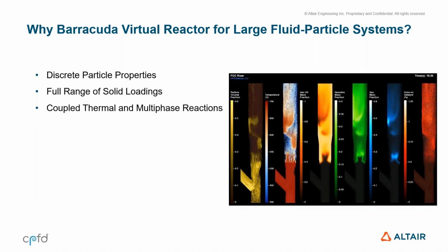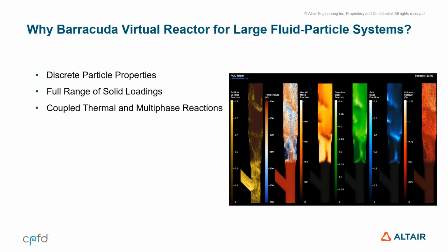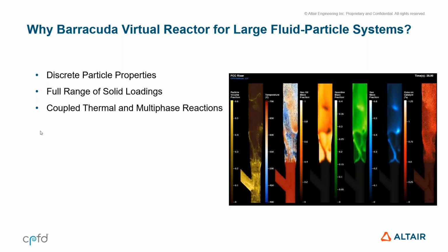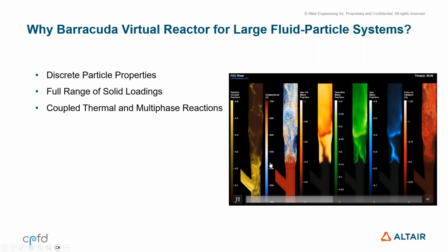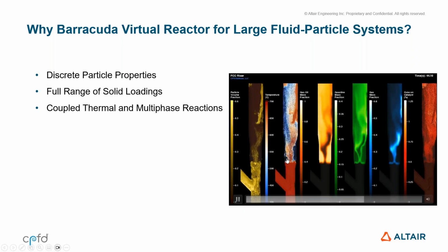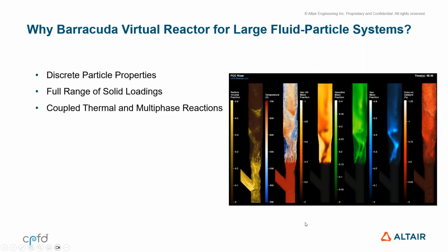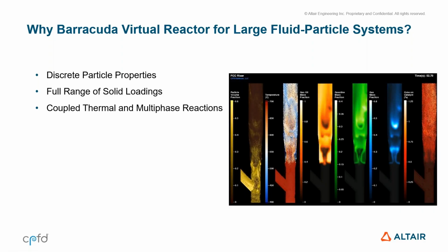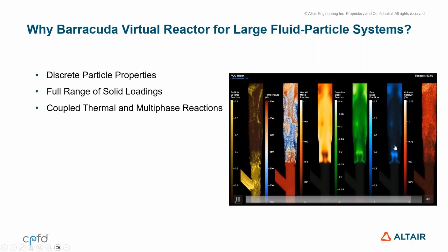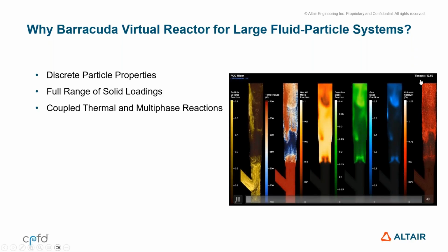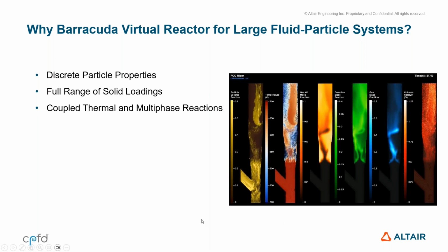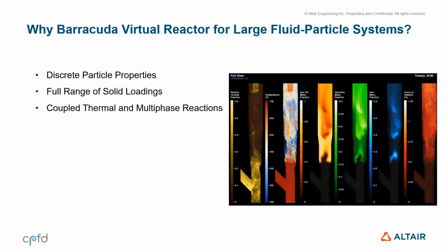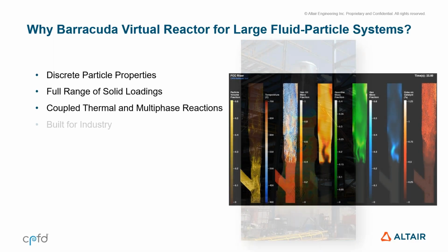And this is coupled with the thermal, the heat transfer, and the multi-phase reactions. In this example, we have the gas particle motion here shown on the left, and then the heat transfer. You have a hot regenerated catalyst, cooled as the vaporized droplets come in. In this case, a very simple four-lump model showing evolution of various gaseous species while depositing coke on the catalyst. So the reactions are multi-phase, both in this case in the gas and on the particle level.